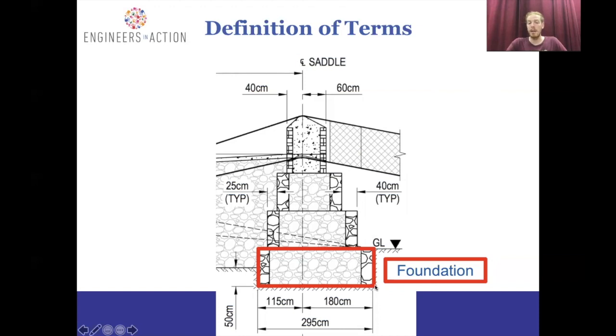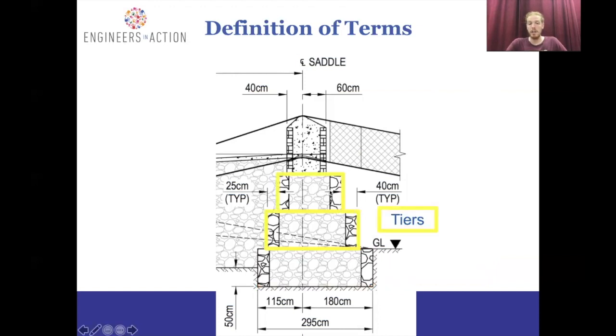Depending on the number of tiers that you have, these other building blocks, that determines the size of your foundation. Like I just mentioned, there's a couple other building blocks that we use in our standard bridge designs. These are the tiers. They look similar to the foundation blocks in this drawing, but here we have 2 tiers, and they're each 1 meter tall, and they get built on top of the foundation. Why we build these tiers is we want to raise our cables up to a higher level, so we get more freeboard, which I'll go over in a moment. So that's the purpose of tiers.